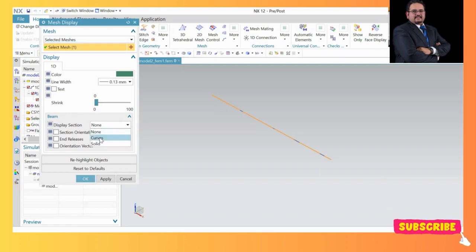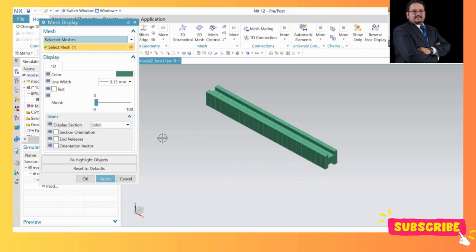But if I say show me the solid display, and say okay or apply, you can see that now you see the cross section I have assigned, right? So this is the cross section assigned. If you keep the solid on, it will show you the I-beam. So your line looks like a beam, whatever you have assigned, right?